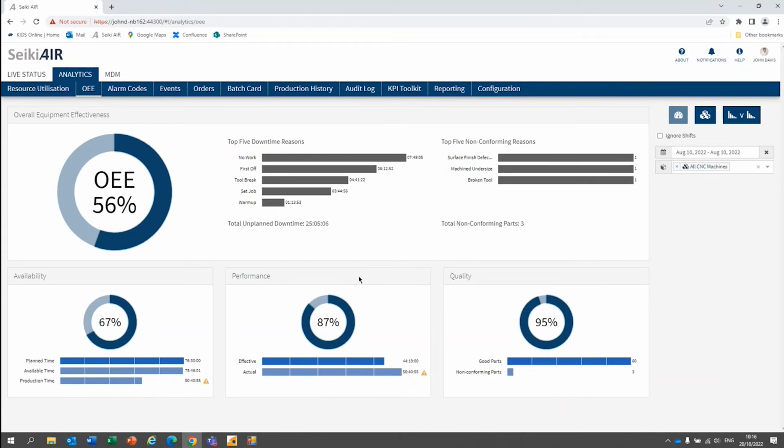in which case real OEE is a bit more relevant. But going back to my example previously, let's say you've got some large components on the machine with 4, 5, 6 hour cycle times. So at the end of the day, the operator might not even have completed the first part, in which case there's no point looking at OEE today because you won't have produced anything. So you need to look at it over a couple of days or more likely a week's basis.